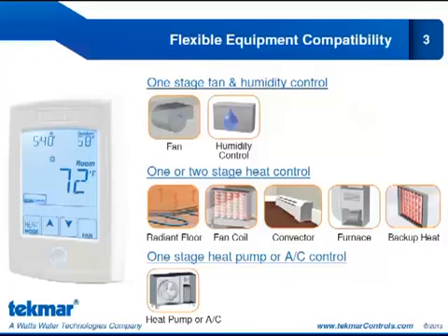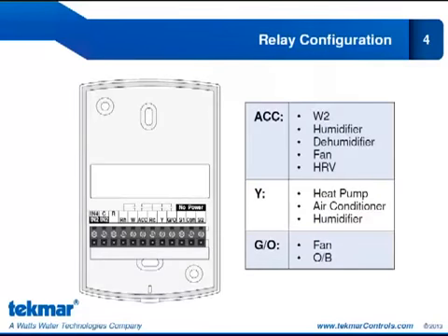So there is a lot of equipment compatibility for the 553, but you have to remember you cannot control all of these pieces of equipment at the same time. And that has to do with the relay configuration for this thermostat. So let's review the relay configuration. You can see right away why this thermostat is so flexible. We can control a lot of different pieces of equipment with these relays.